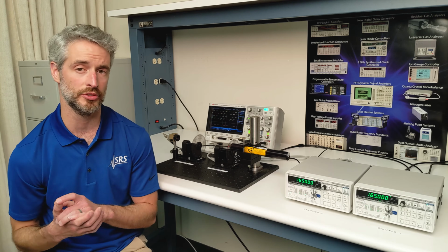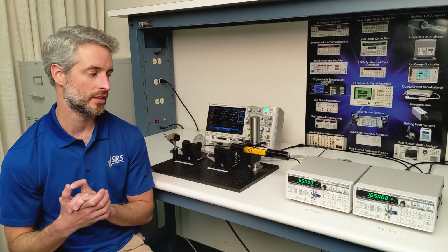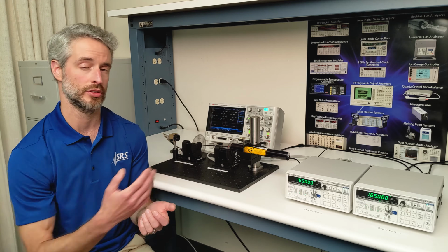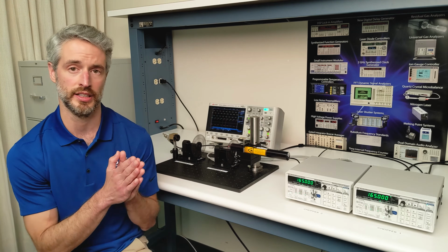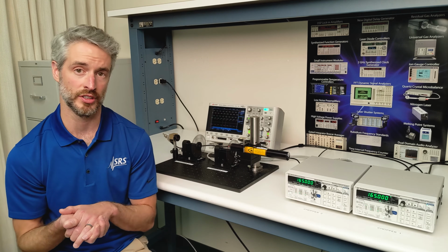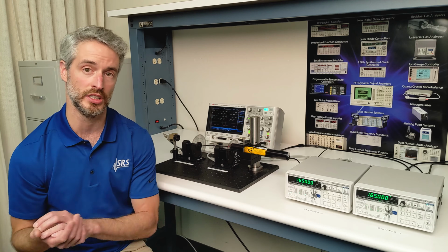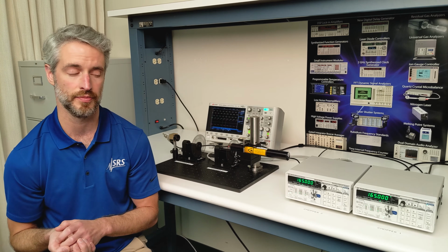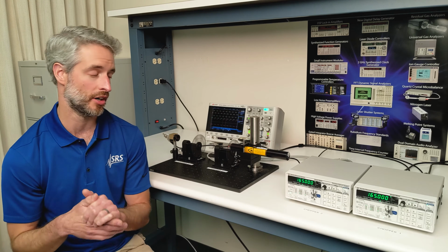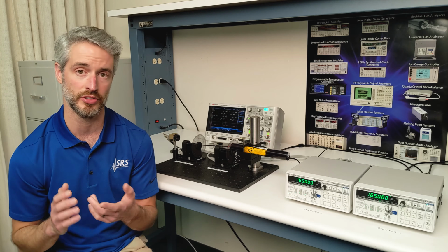In conclusion, when it comes to control of duty factor, using two optical choppers is better than one. Because of the excellent motion control provided by the SR542, synchronizing two choppers in this way is functionally identical to mounting two blades on the same chopper motor, but you get the added benefits of high precision and repeatability and the ability to digitally control the duty factor on the fly. You can use this method with any of the blades that are compatible and offered for the SR542 in order to optimize the setup for your chop frequency and beam size.